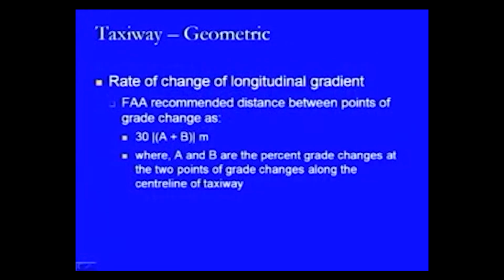So, these A and B are the percent grade changes at the 2 points of grade changes along the center line of the taxiway. So, this is another recommendation and guideline provided for the provision of the different grades, and at the same time so as to maintain a distance between those changes of the grades.